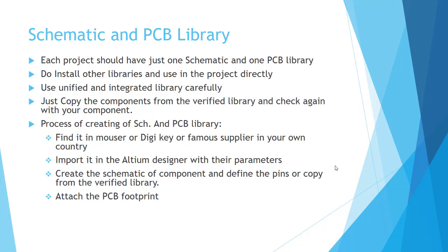After that, attach the PCB footprint. In this stage, be sure to check the PCB footprint. After that, use it in the schematic design. For the rest, I will describe these procedures in the Altium Designer project.